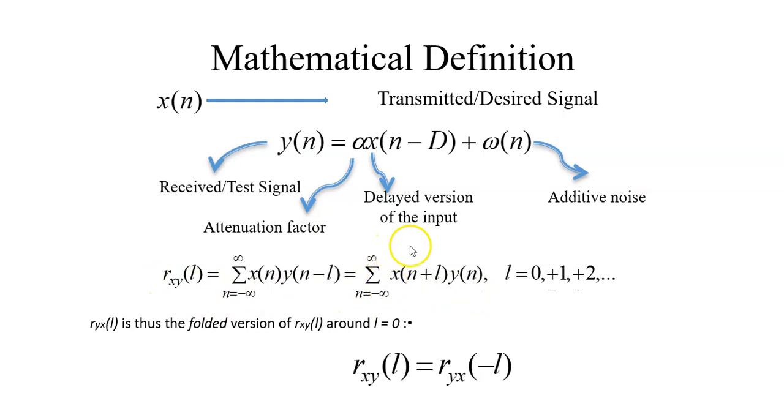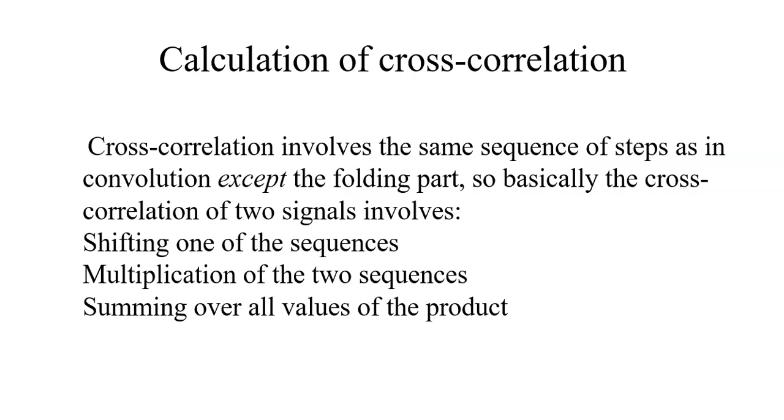And see, this is our output. This is the cross correlation of x[n] and y between them. So the maximum correlation will be 1 or minus 1. If they are 100% similar, which means they are the same, we have 100% correlation. If they are orthogonal, we can have 0, and if they are the opposite, or what we call antipodal, they will have cross correlation maximum but in negative value.